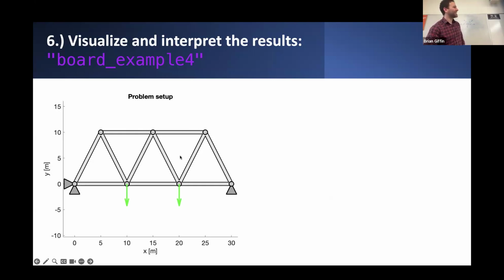Yeah, intuitively, I'd want to say they're all tension, right? You're shaking your head though. Think the two diagonal members, the middle, one is in tension, one is... Well, could that be possible? No, because of symmetry. Because the loading is symmetric. If the loading was not symmetric, then anything's game. But in this case, what do you think? Tension or compression for these middle ones?